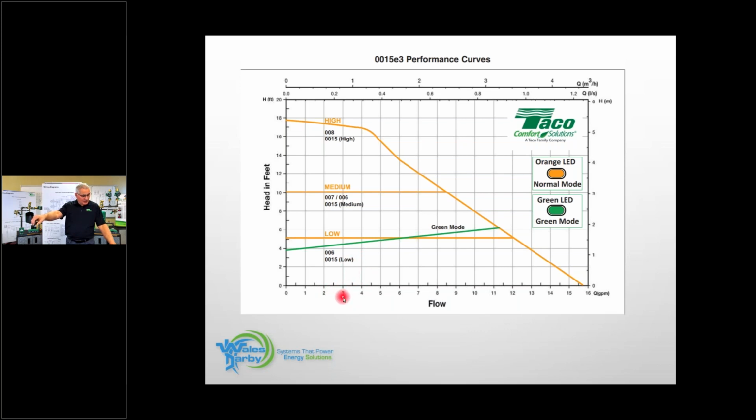That's good. The next one, 3.5 at 5 and a change. Again, that gets me on the low side. 3.5 at the 6.12. Well, by math, I should say medium, but I could live dangerously and put it on low. And the 122, that's going to get me to medium because we're at 7 and change. And the 151 is going to get me at 9. I could put it at medium. So I can have one circulator and just change the speed based on zone size. This is the advantage of having the variable speed circulators.